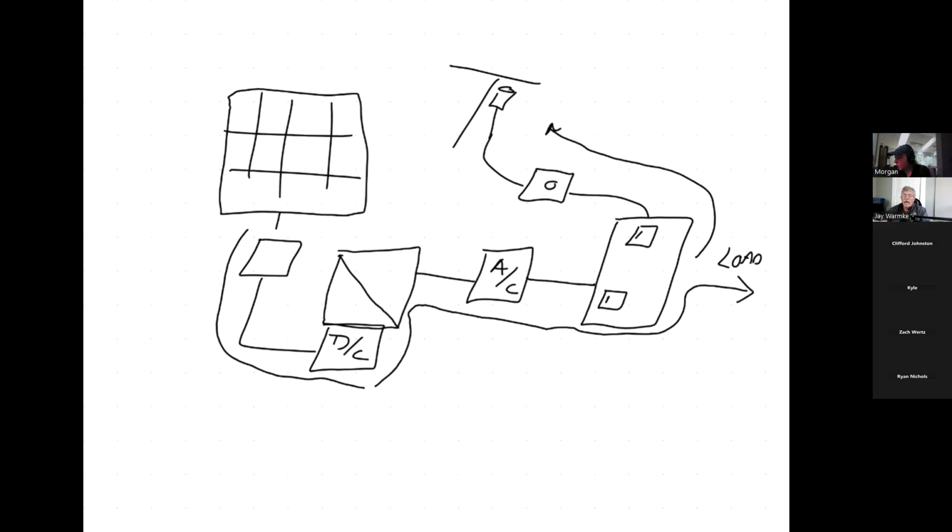And then it's going to drop, and that's going to cause nearby transformers to kick off because you're falling outside of the operating range of the system. And so that one kicks off, which makes the problem worse. And then you get these cascading transformers blowing. So then you end up with the grid shutting off.